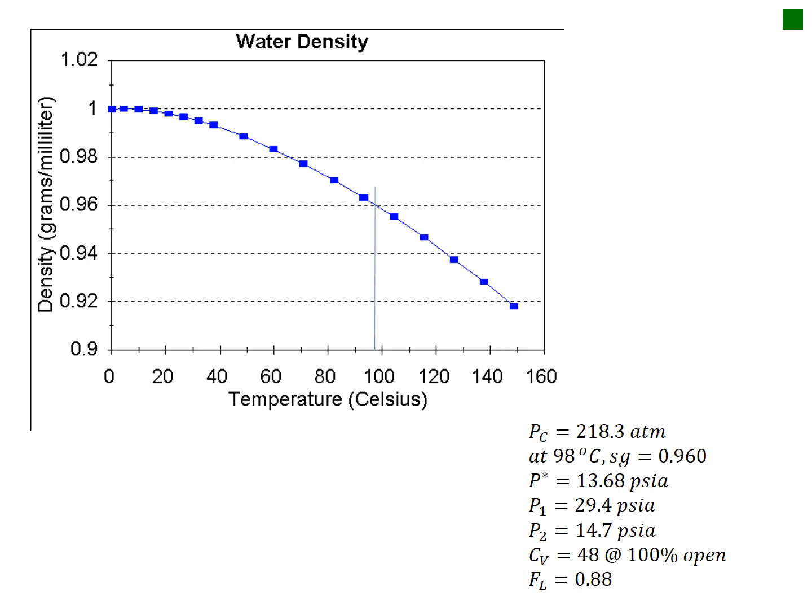We need to know what the density of the fluid is traveling at the system temperature. And so here I got some data off the internet, which tells me the density of liquid water as a function of temperature. And at 98 degrees C, we will find that our density in terms of grams per milliliter is equal to 0.96.